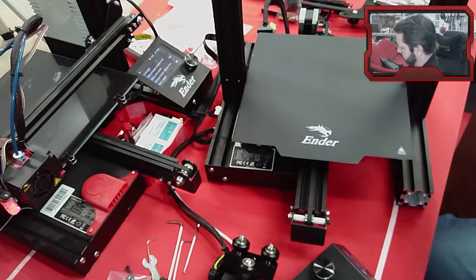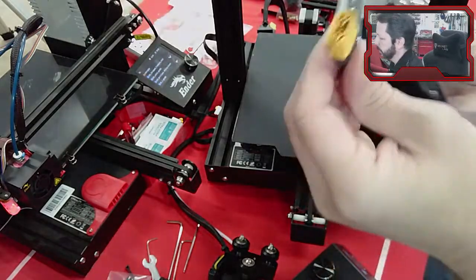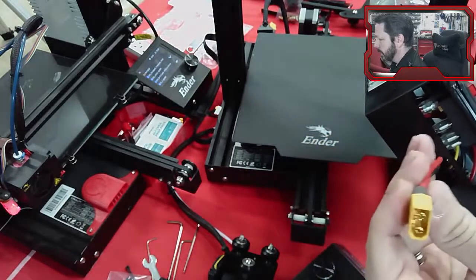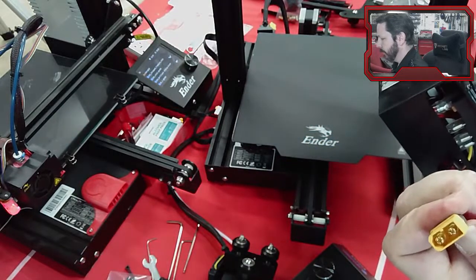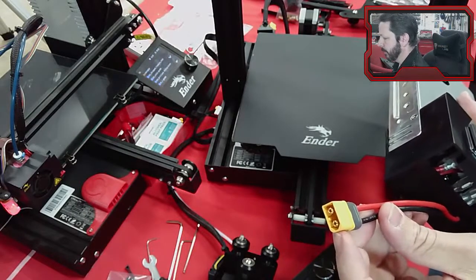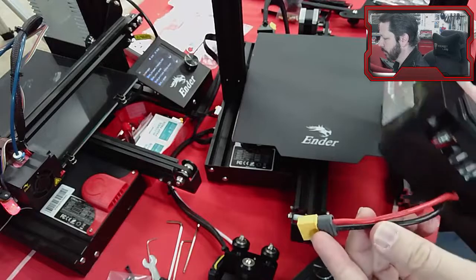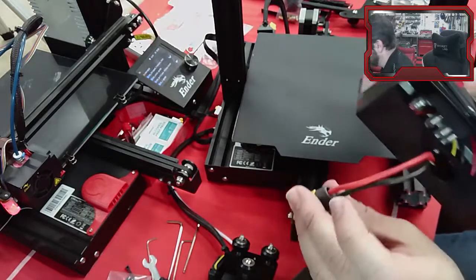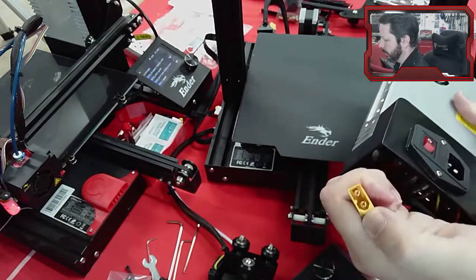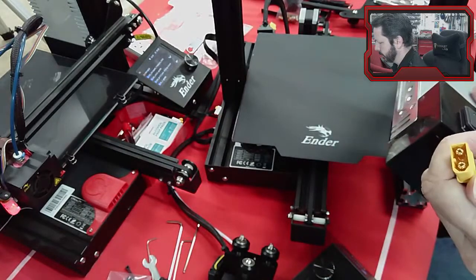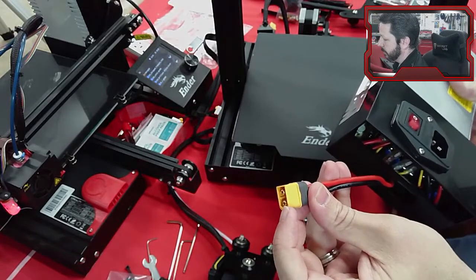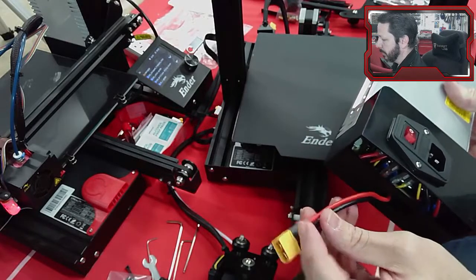Oh, mine's got some wires. Oh, so this guy. This is the source on some kits. I haven't seen many lately, but when they first started making these Ender 3s, they would use an unofficial version of this, and they would solder the connections. These do not look soldered. These look crimped. So you want a real XT, what is this, XT30, XT60? XT60 connector. And you want crimped connections.